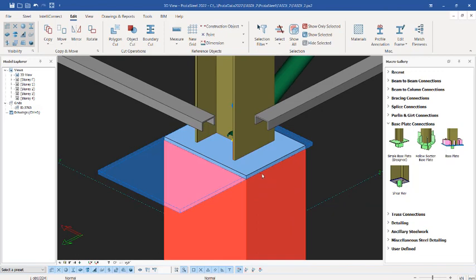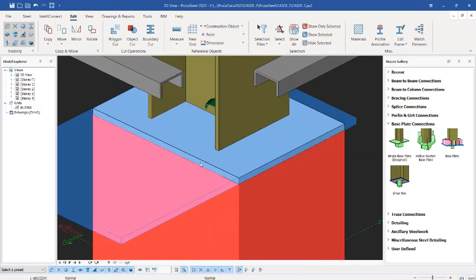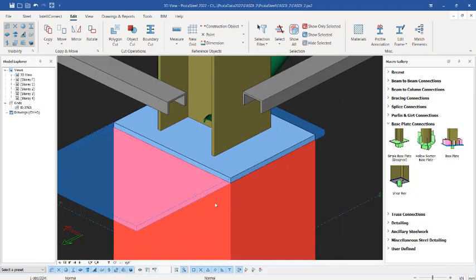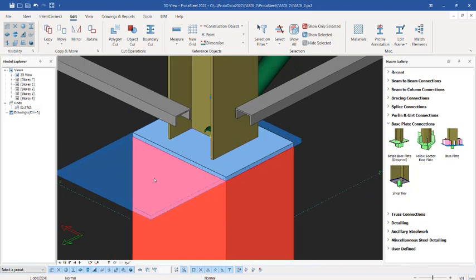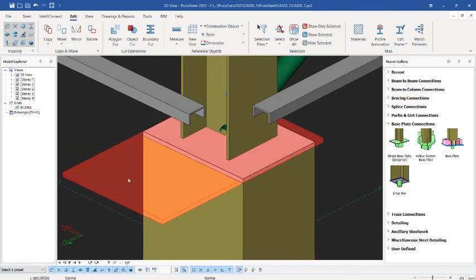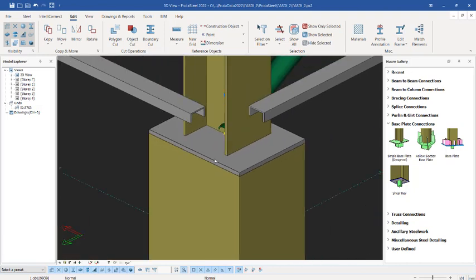All right, so with this now, if you carry out a clash check, you will notice that there will be no clash between the reinforced concrete column and the plate, because we have cut the part that is clashing out. This is an auxiliary file, or an auxiliary macro, this cut symbol, so you can also remove it. If you want to remove it, you come to these provisions where you have this one. Click on it to remove that. So this is the plate itself.